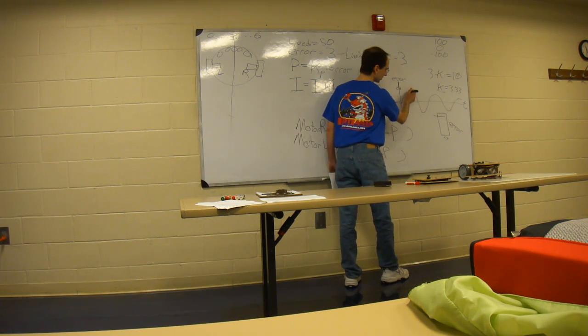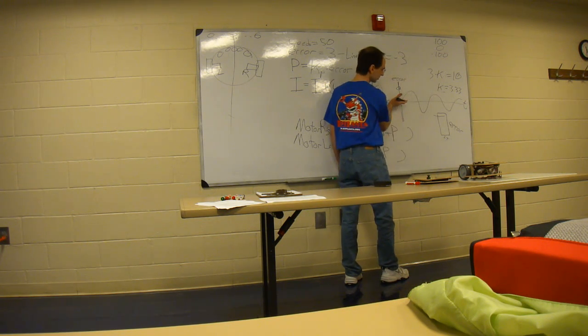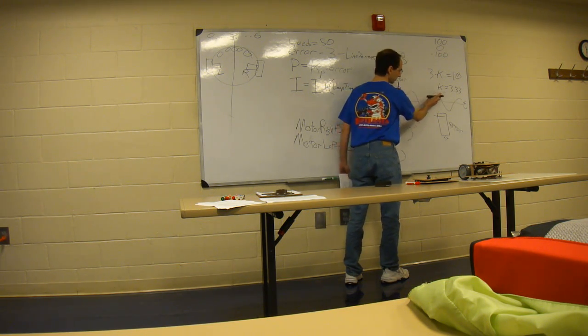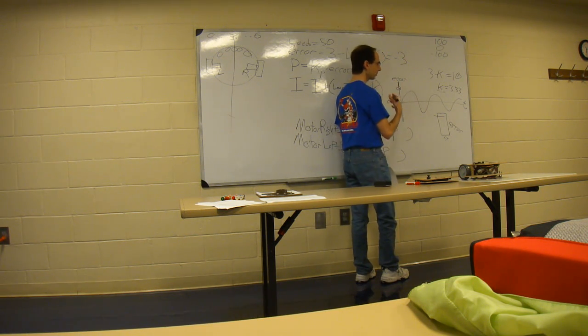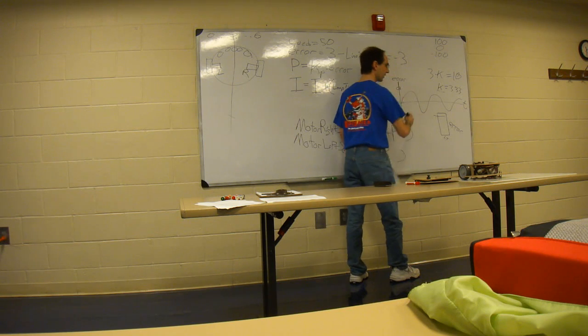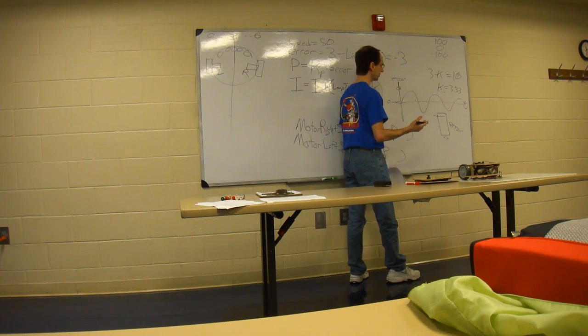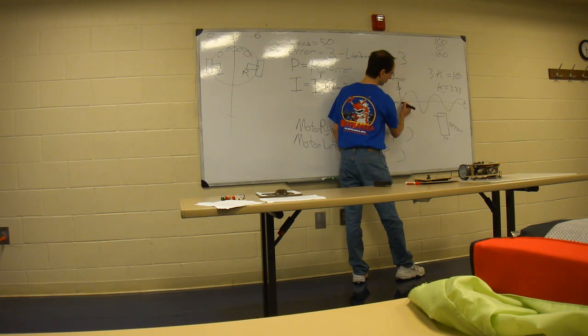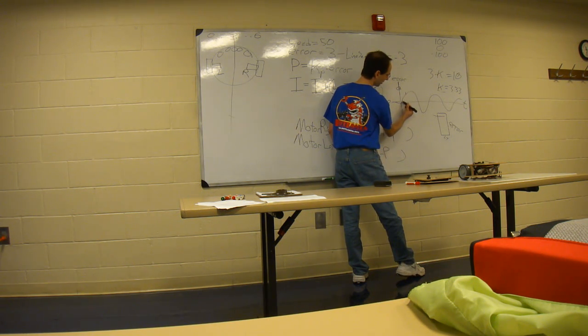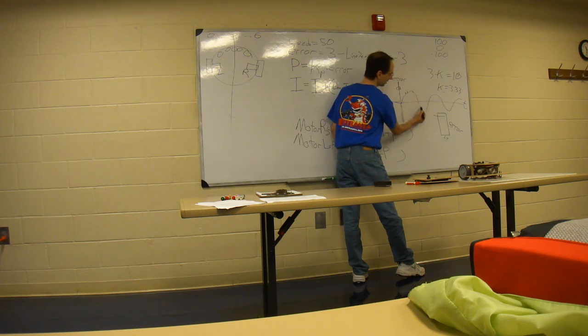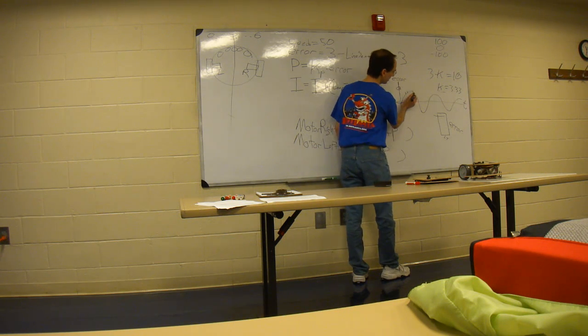We can get a proportional feedback from just looking at the position. We can look at the area under the curve, but we can also look at the idea of how much the error is changing per unit time. For example, between here and here, the error is rapidly increasing, while between here and here, the error is pretty much steady. And then between here and here, the error is rapidly decreasing. That's very powerful information because, for example, here we know we're rapidly approaching 0.